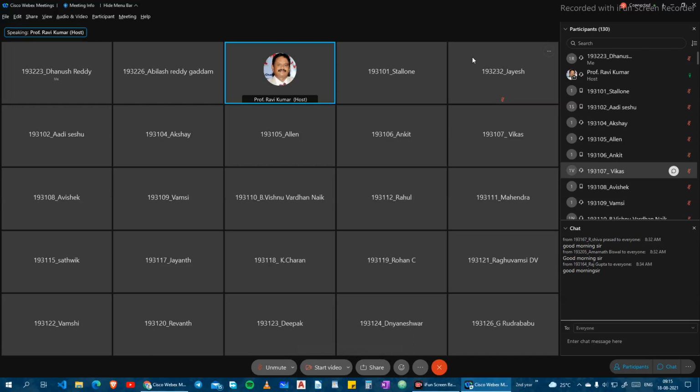Once the cycle happens, power is automatically generated. The power is stored in the flywheel and used during the inlet, compression and exhaust strokes, but power is generated only in the power stroke. That's why the flywheel is very essential for a two-stroke engine, a four-stroke engine, any engine, for storing energy. The flywheel plays a vital role in keeping the cyclic process going.